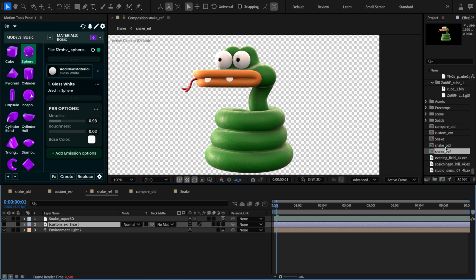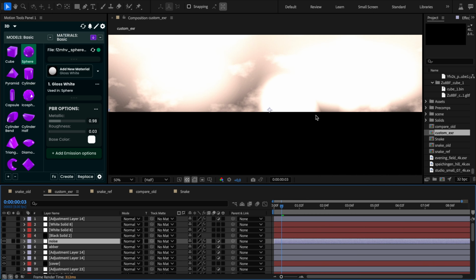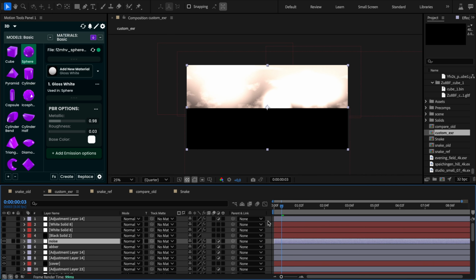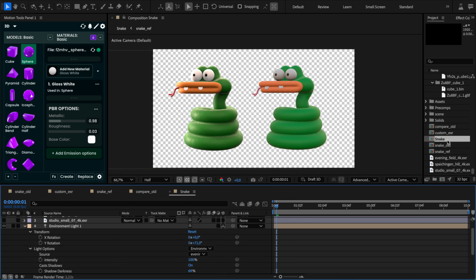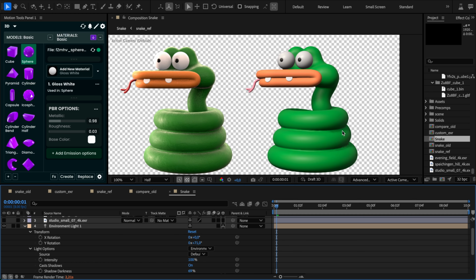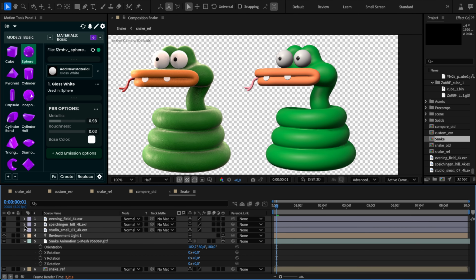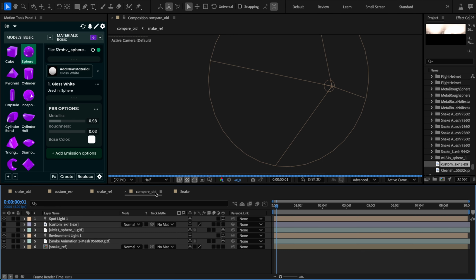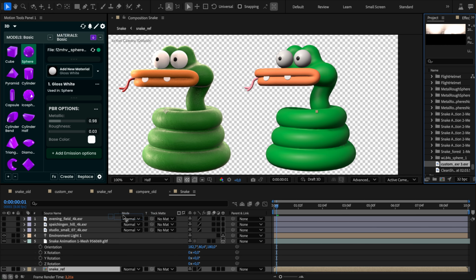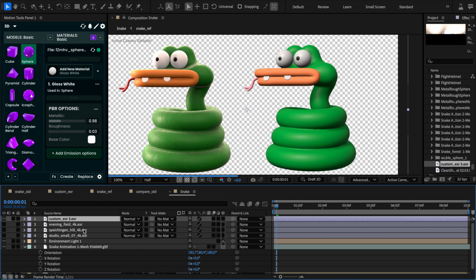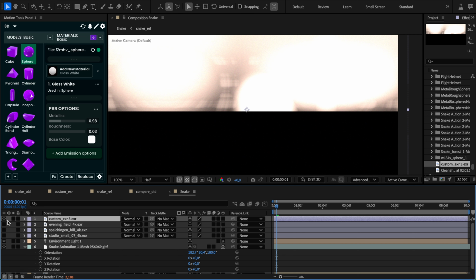Creating custom HDRI and EXR maps involves combining various light sources and environments to achieve the needed look. In Photoshop, you can merge different images and adjust their brightness and contrast to create an HDRI map. In After Effects, you can use layers and effects to build a dynamic environment, then render it as an EXR file. This is one of the main components for developing a great look: lighting, materials, and some color corrections.